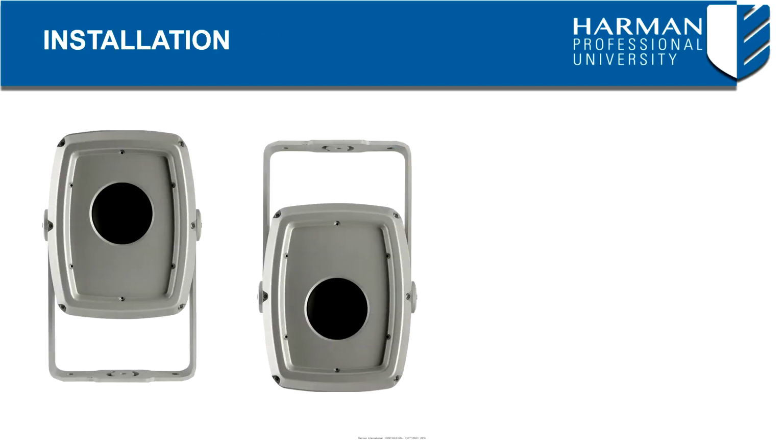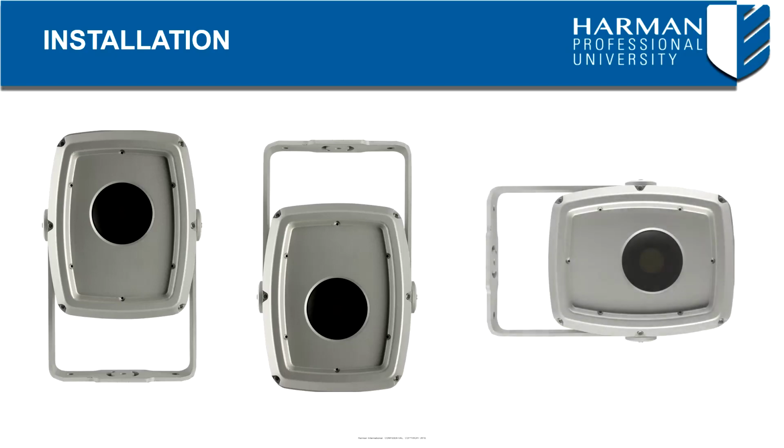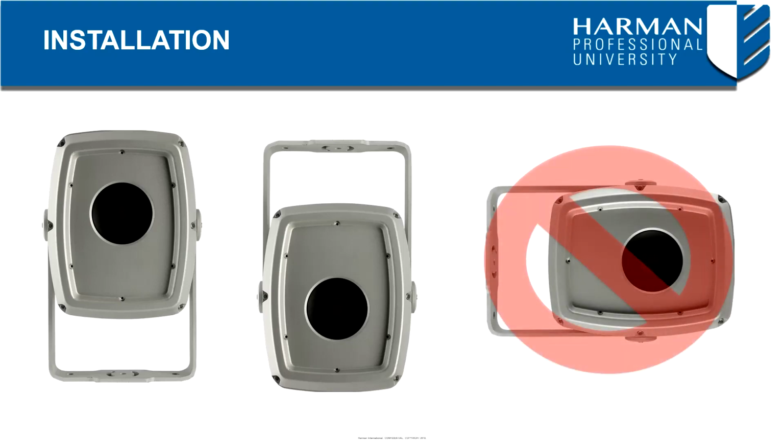The exterior projection products can be mounted at any angle, and the yoke can be fastened to a vertical, horizontal, or angled surface. However, make note, the sides of the fixture must be vertical when installed, or the fixture's cooling airflow will be affected, leading to reduced light output, as the fixture will automatically reduce the output to accommodate for the poorer cooling.